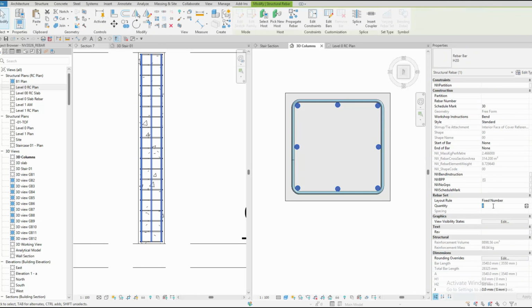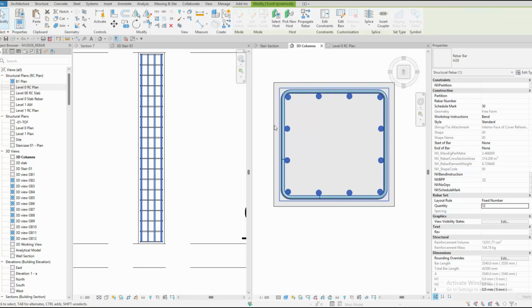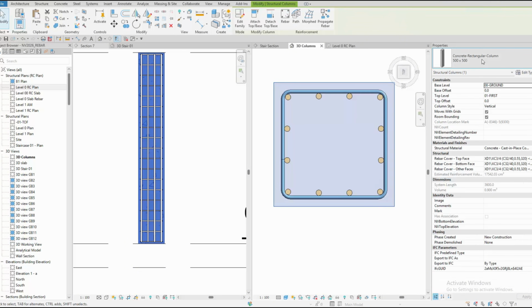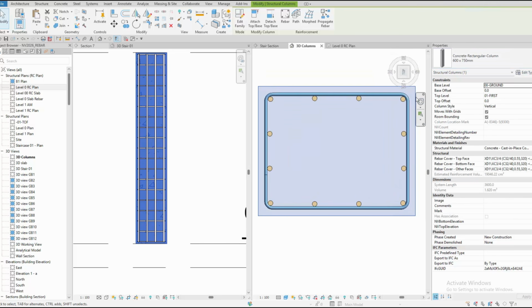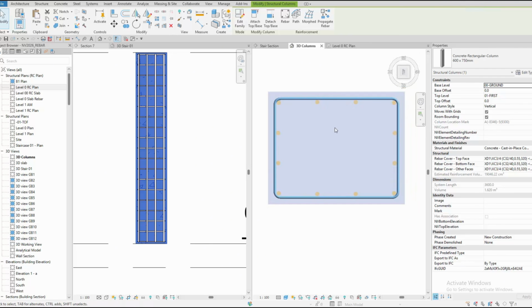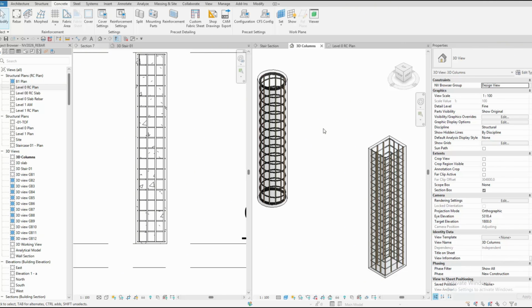So of course if I set this to 4 rebars in here, that's our result. Yep, if I go for something like 12, again you can see those results. So this is a really good way of modelling this main rebar. And of course, like everything else, this is completely parametric. So if I went back and changed the actual formwork here to something different, you can see the main rebar links have all updated, as well as all the main reinforcement in that column. So that's a really good use case for reinforcing typical structures.